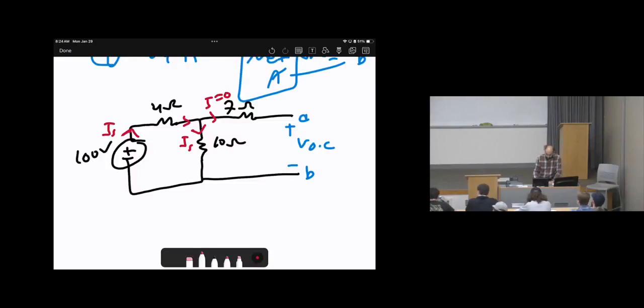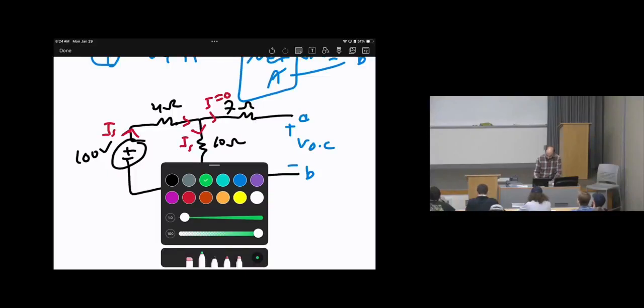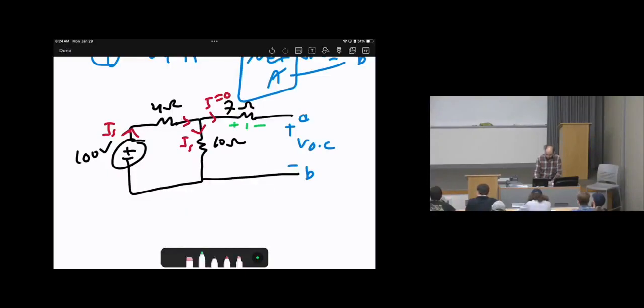Now, look at the 7 ohms resistor. What will happen to the voltage of the 7 ohms? V7 ohms equals I times 7, right? Which is I times R. I, we said it is 0. 0 times 7 equals what? 0. So, since now in 7 ohms, I equals 0, V equals 0, therefore erase it, discard it.